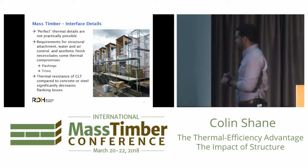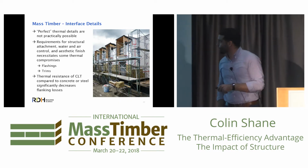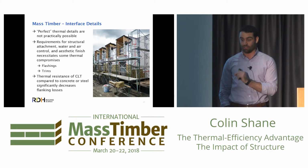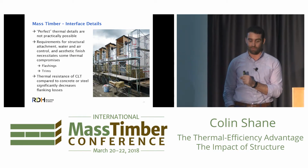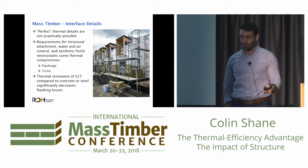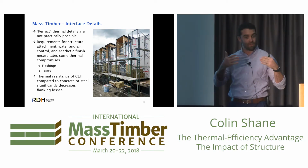Mass timber, these interface details in mass timber, what's the difference? Like I think I alluded to, the perfect details that may exist that give us really good values for linear transmittance at interfaces are hard to achieve in real life. There's going to be some trade-offs we have to make. We need to hold stuff onto our building. We have attachment considerations, right? We need to deal with air and water. We have metal flashings and things like that that can really compromise getting a perfect alignment of our insulation